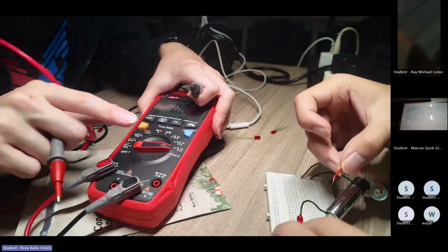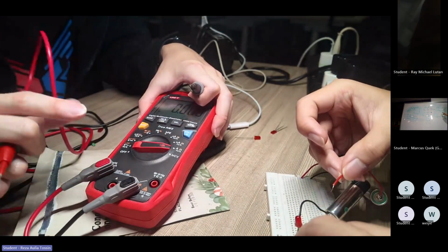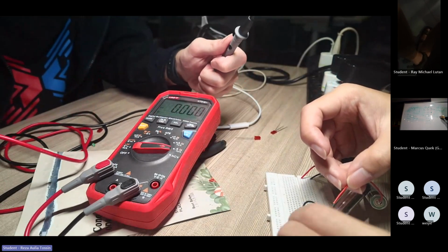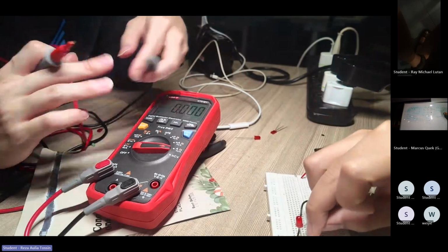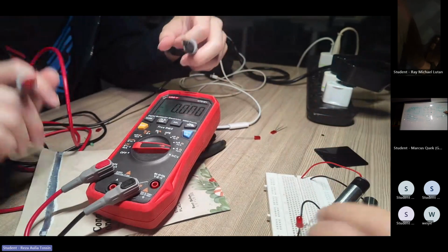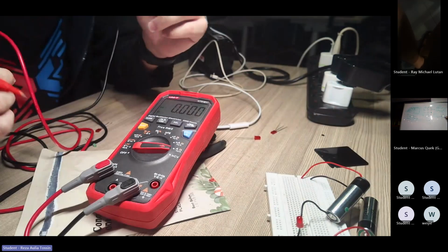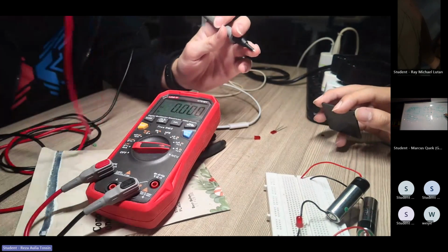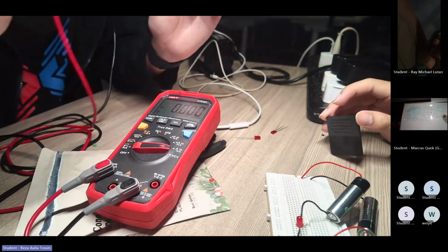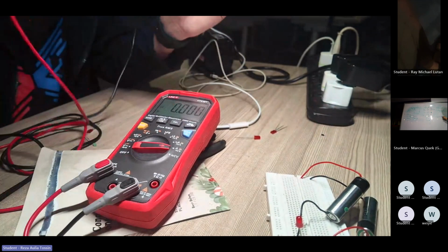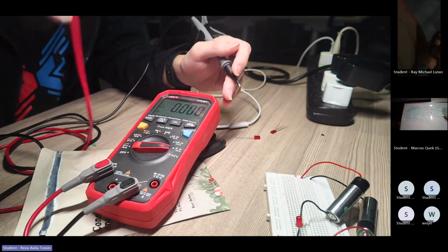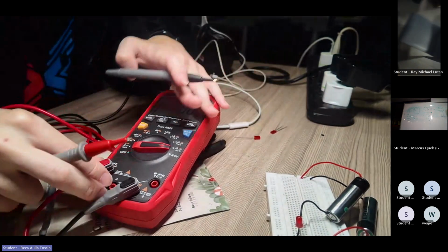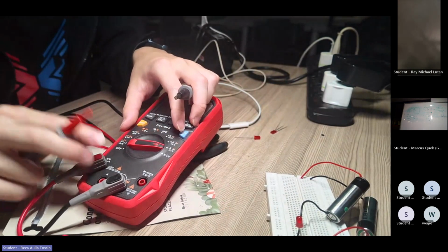Be careful. So never leave the thing in current mode, because current mode is a dead short, because an ideal ammeter has zero resistance. Usually people measure voltage first, so they're going to take the voltmeter. An ideal voltmeter has infinite resistance because you put it across, so you shouldn't have current going through the thing. If you leave it in current mode, it's a dead short. Someone's going to put this across their circuit and short their circuit. You're gonna have a crap ton of current going through this. This is not ideal. It will just blow up. So never leave this in current mode. Always put it back to voltage mode.